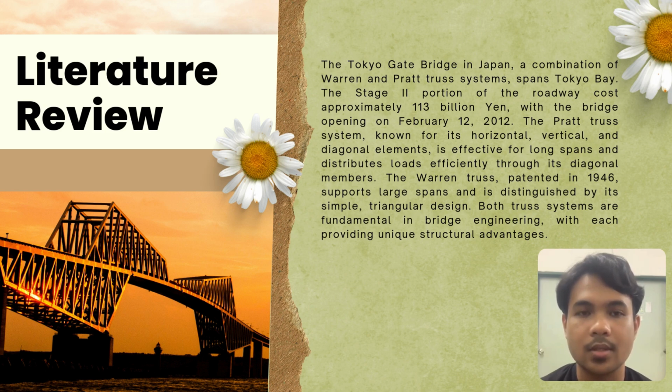The Pratt truss is characterized by diagonal members sloping outwards from the bottom to the top chord, contrasting with the inward slope of the Howe truss. It supports longer spans and heavier loads due to its efficient design, which equally distributes forces across vertical and diagonal elements.